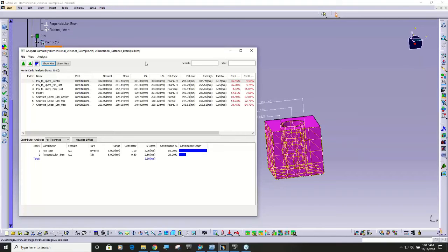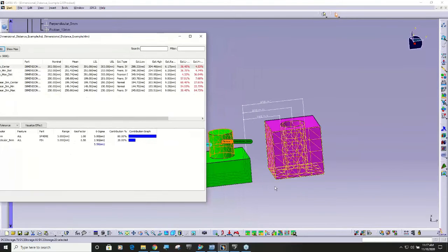The dimension distance measure is looking at the top, middle, and bottom of the hole or pin, and then it's measuring it along the vector from the feature picked. So this one here would be measuring normal to this surface from here to this point, this point, this point, and then outputting the minimum, if it's up here or down here. So it's different than the feature measure, and it wouldn't pick up, if you had some kind of bump in the center here. It's just going to look at the 3 spots.